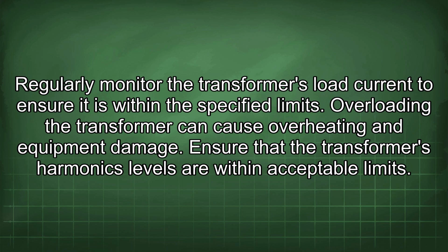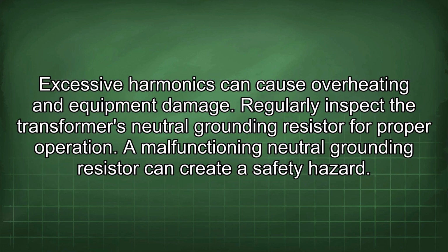Ensure that the transformer's harmonics levels are within acceptable limits. Excessive harmonics can cause overheating and equipment damage. Regularly inspect the transformer's neutral grounding resistor for proper operation. A malfunctioning neutral grounding resistor can create a safety hazard.